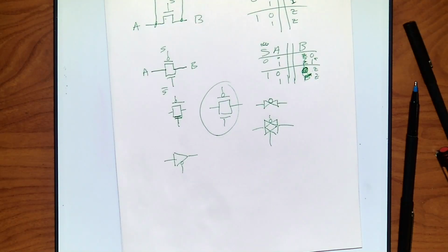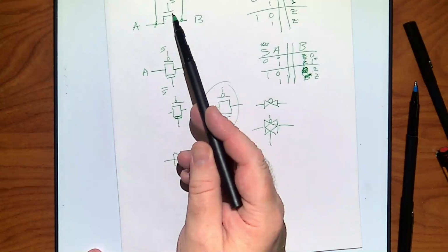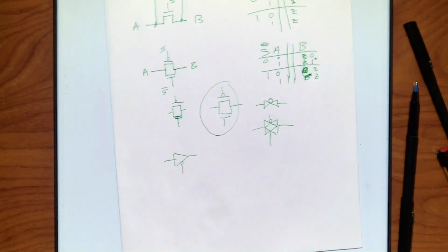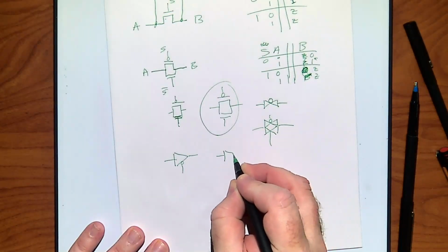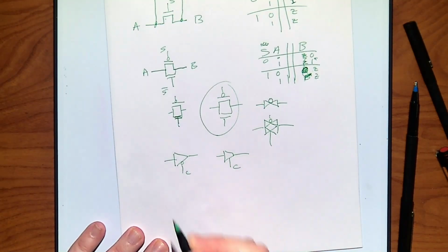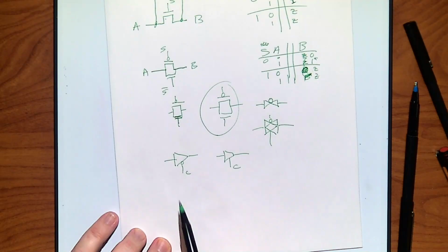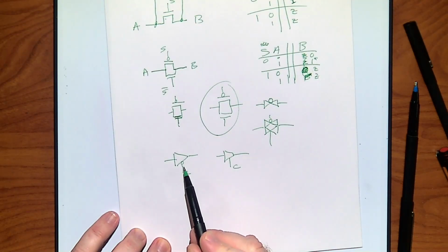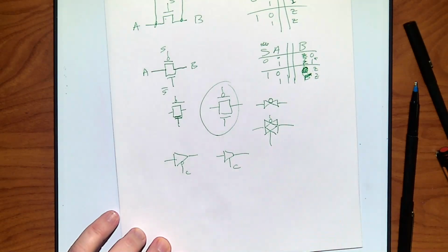This is a gate. You might have seen in digital logic, hopefully. This is called a tri-state gate, right? So a tri-state gate could be built as one of these or the other, or as a transmission gate. There are 2 forms to tri-state gates. And really it's just a control which operates off of positive or negative. And if the control is satisfied, so if it's a 0, it's open. If it's a 1 on this one, it's closed. That's essentially what we just did here.